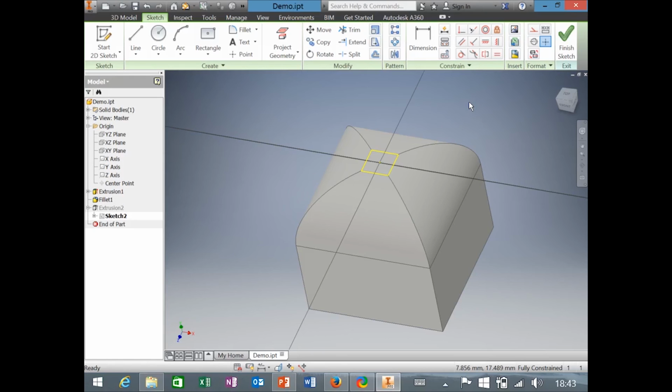One thing that I will warn you about is that fillets are especially finicky. I have found myself in situations where I had a very complicated set of fillets and I adjusted a dimension and Inventor will just crash on you. So be really careful about that. I've only seen it happen when you enter the fillet to edit it. So if it complains to you and tells you that the fillet dimension or the fillet parameters are somehow screwed up, save your model immediately because it's going to crash.